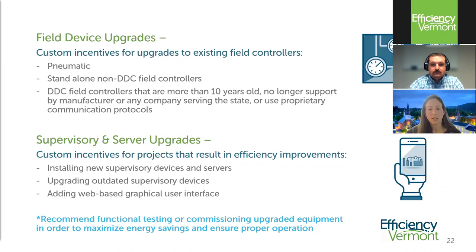Just as a note here, we recommend that functional testing or commissioning be part of a controls equipment upgrade in order to maximize energy savings and ensure that everything is operating properly.